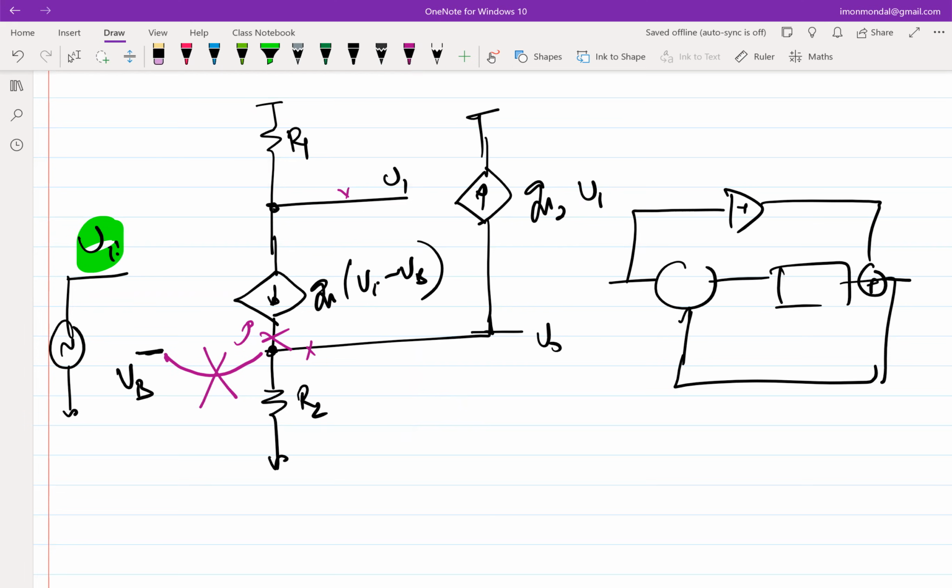So as it turns out, there are multiple ways of analyzing feedback networks, and each one of them has its pros and cons. I haven't talked about return ratio in detail, but if you want to look it up, you will see that return ratio gives you exact output, but it's at the expense of figuring out what is the amount of feedback, where can you apply it and how can you stabilize the circuit, and so on and so forth. So most circuit design courses and most circuit designers stick to this loop gain approach, even though it is slightly more erroneous.